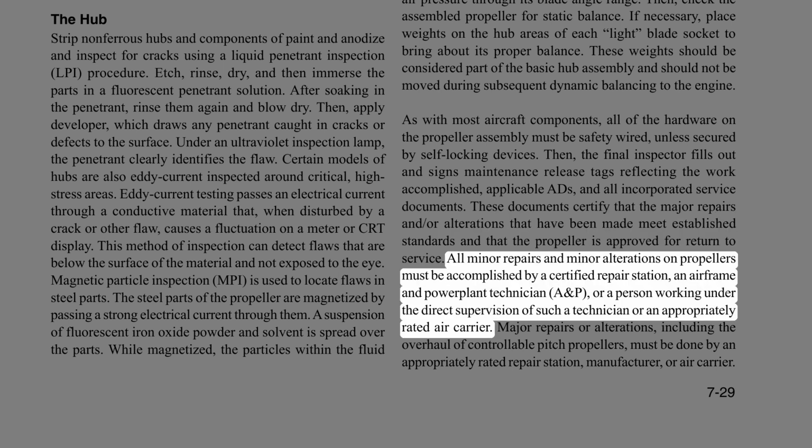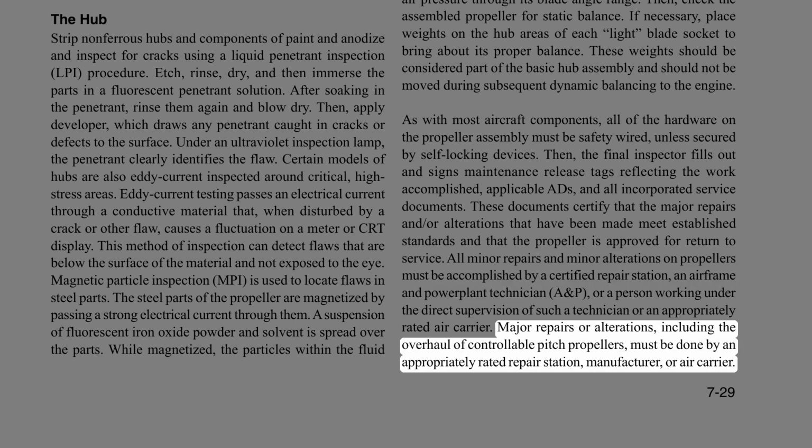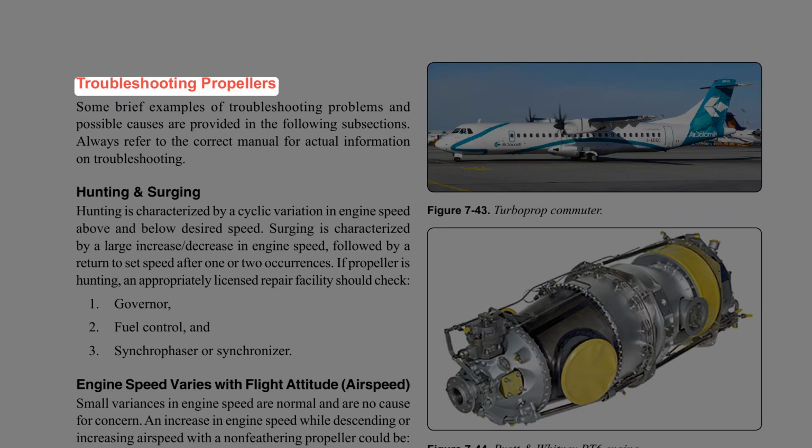All minor repairs and minor alterations on propellers must be accomplished by a certified repair station, an airframe and powerplant technician, A&P, or a person working under the direct supervision of such a technician or an appropriately rated air carrier. Major repairs or alterations, including the overhaul of controllable-pitch propellers, must be done by an appropriately rated repair station, manufacturer, or air carrier. Troubleshooting propellers.